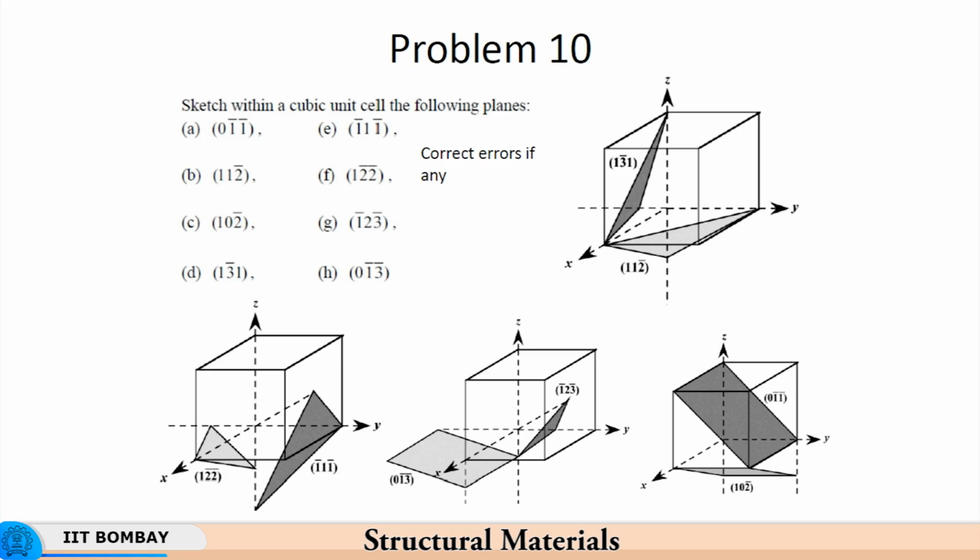Here, for example, this plane is going outside the crystal lattice by a little margin. Had the origin been shifted to here, this is 1 bar 3 1, this plane D 1 bar 3 1. So, 1/3 is the intercept, -1/3 is the intercept here. So, you would have got 1 bar 3 and 1, as another triangular plane over here. Basically what it means is the plane has to be drawn by shifting the origin. So, the error here is that the origin has not been shifted.